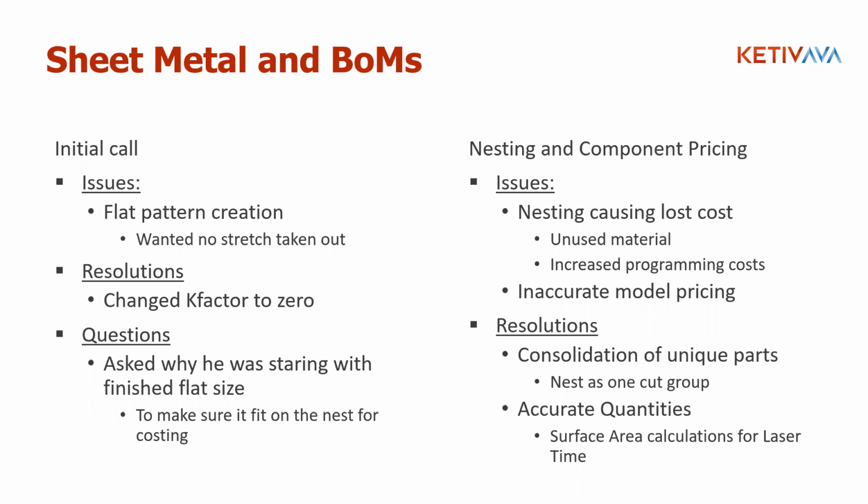And so I was explaining that if you roll all the parts into one nest and cost it as one part, because they're all welded together, you can give them individual names, but when you cost it in your ERP and for nesting, it's one thing. I was asking him, do you ever plan on cutting out two bracket A's, but only one base plate? He's like, no, it has to go together. I'm like, well, if you do it this way, it's not guaranteed, because there's no such thing as guaranteed in manufacturing, but it usually lends itself to keeping it more accurate 1-to-1.